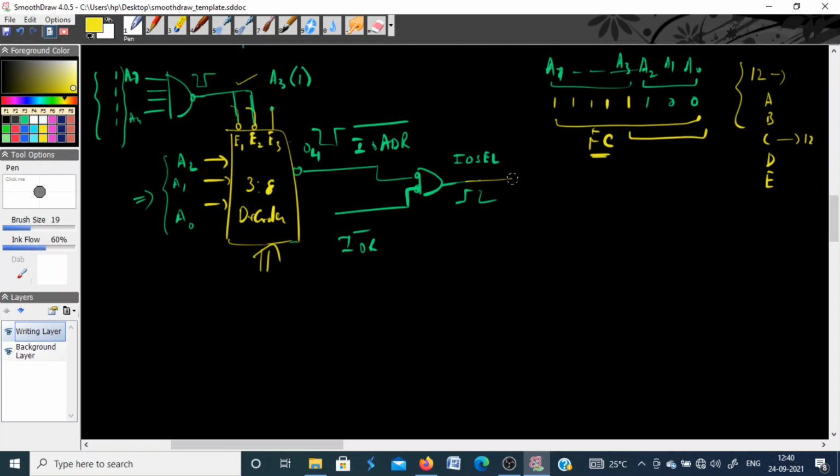Okay. So now this is connected to the enable pin of the buffer. So as input you have DIP switches, and the output of the buffer will be connected to your data bus. So through this data bus, the data will come inside the microprocessor depending upon the position of the switches that you connect here.